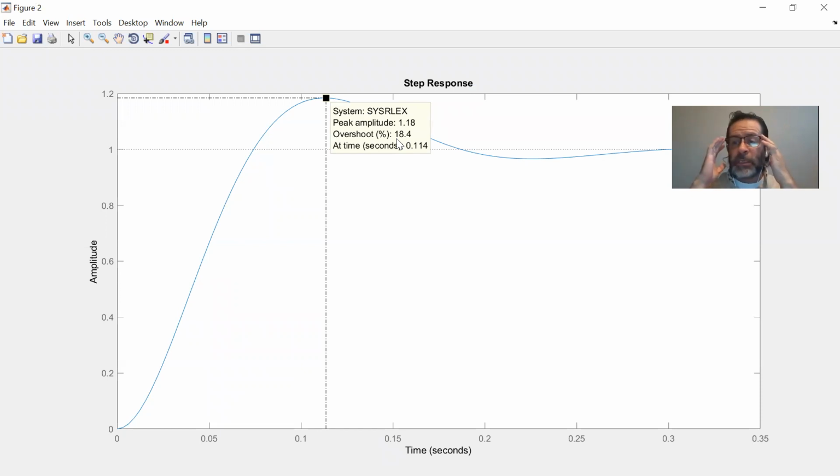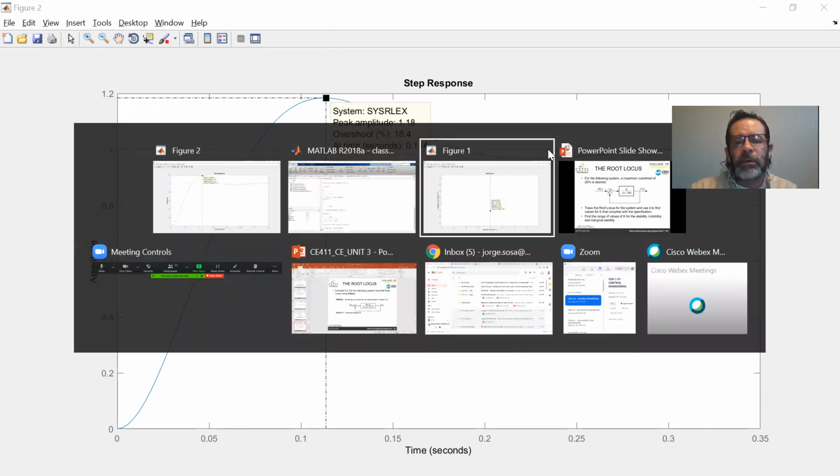And if you notice, with the root locus and using MATLAB as a tool, we can really play around with these values, and it can help us define these ranges for our system for different values and different performances. Okay, so now at least I know that if the value of k for a 20% overshoot is 1080, now I can play around with that, and I know that at least if I give it lower values than 1080, the overshoot is going to go down. So that can be an interesting design parameter or tool, rather.